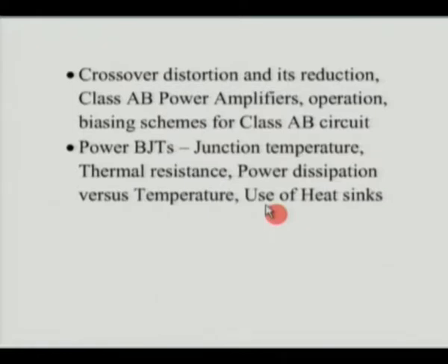One very important thing to remember in this topic is that the transistors we use here are very different from the ones we were considering so far, hence the word power BJTs. So far the BJTs we were using were what are called small signal amplifiers, such as BC147 or BC547 or BC109 and so on.